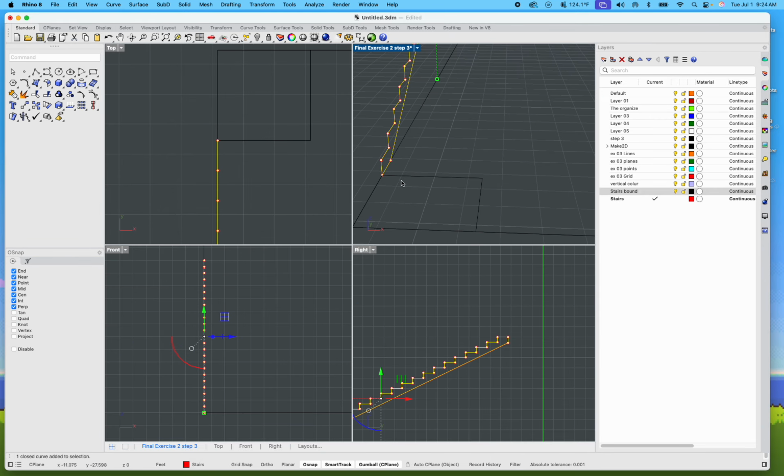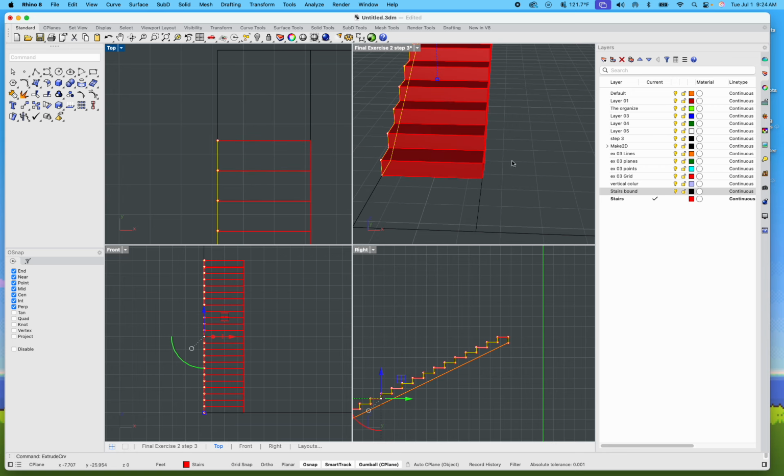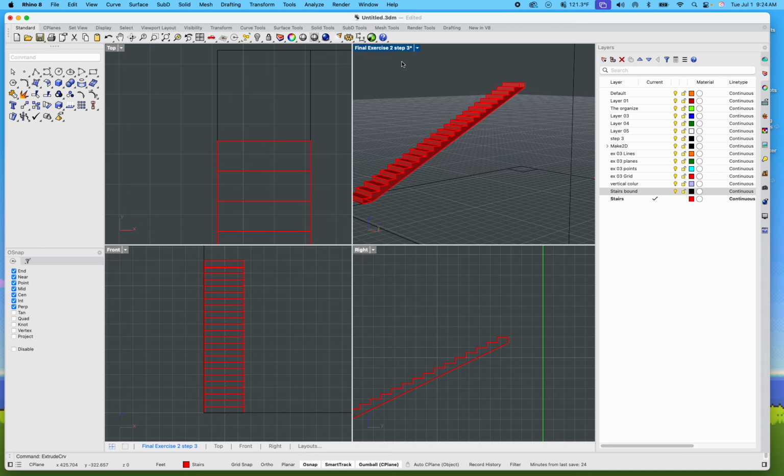I'm going to go ahead and extrude it exactly 3 feet. Extrude. You'll notice there's a couple of options. You can actually make something solid to begin with in this step. You'll notice on the Mac it's definitely to the left, whereas on Windows it's inside these tiny little links, right? Especially if you're on Windows. So just keep in mind the same options are there, both Mac and Windows, but they're in 2 different spots, right? In my case, I'm just going to go to the other side, click, just because I already drew that, and bam, I got some stairs. Let's check them out.